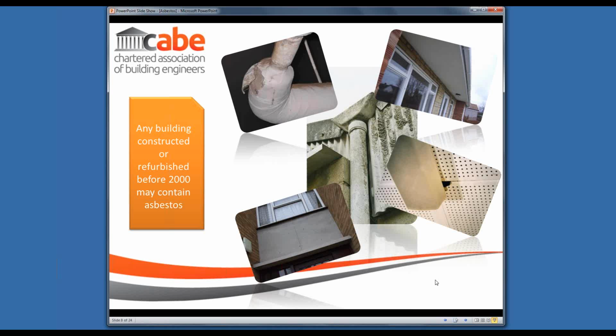An awful lot of existing buildings still have asbestos there, and there is the potential then for that asbestos to release fibres into the air if it is disturbed, if it's damaged in any way, if somebody drills into it to fix something else. There is a potential that those asbestos fibres will then get into the air. So yes, the first word of warning is it will still be there in the vast majority of buildings we're encountering today.